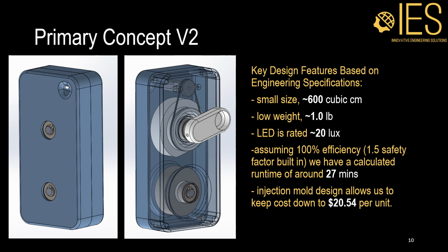As you can see in the CAD renders, the wind-up spring sits on the lower roller. The user will use the handle to wind up the spring onto the upper roller. When the user allows the spring to unwind, it is connected to a generator built-in gearbox through an O-ring driven pulley. We have engineering models that prove that the optimum ratio for the pulley to be 2.8 to 1.